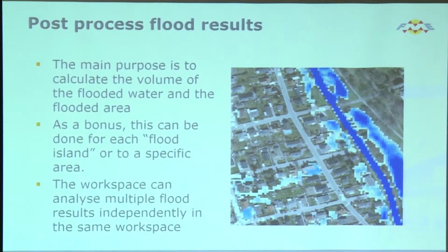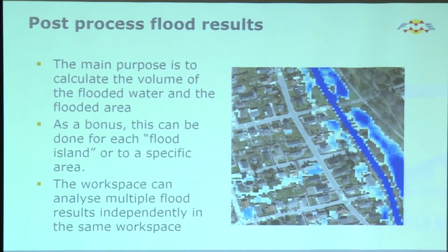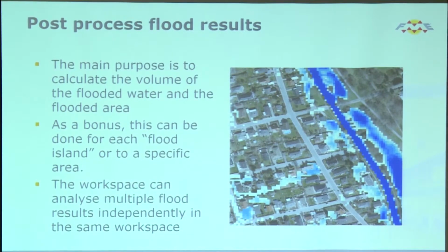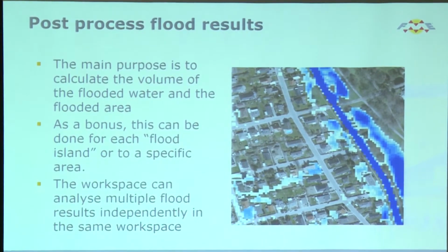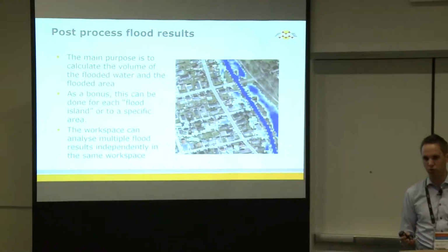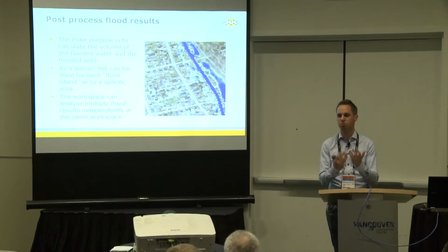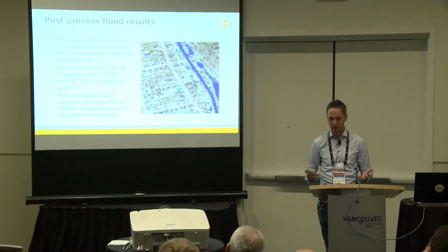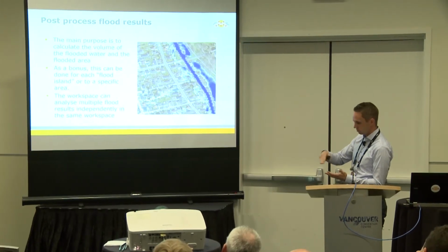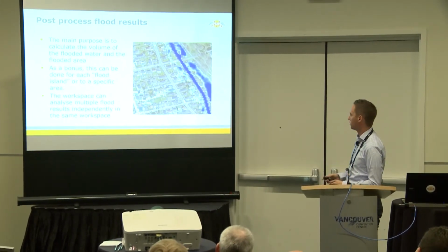The second one is after I've used that DTM now to make some flood calculations where I have both the sewer system and a DTM. So it works like this. If you have some rain that goes into the model, all the sewer pipes get filled up because you have too much rain coming into it, and then it surcharges or gets pressed up to the streets, and the 2D model calculates how the water is flowing.